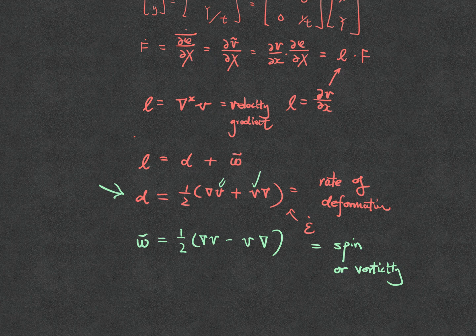It's the fact that if I hold the deformations constant, how fast it changes your orientations. Remember the relationship between the spin and rotation tensor? Do you remember that? Spin tells you the change, linearized in the Lie algebra of the deformations.